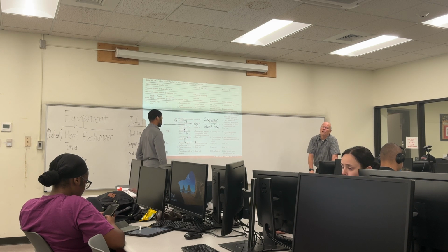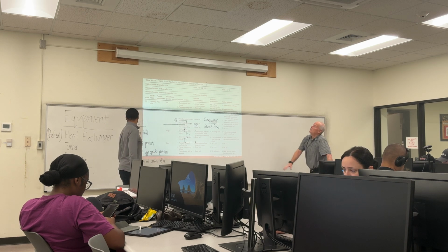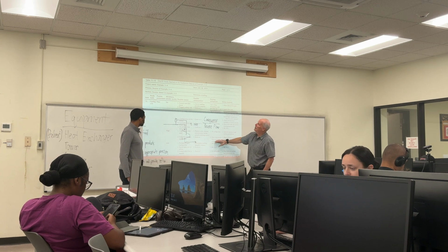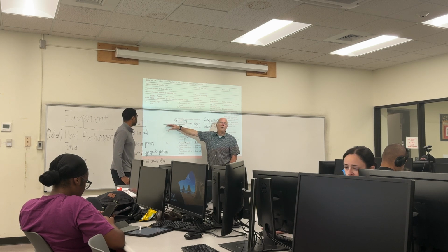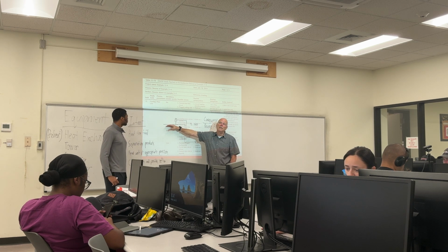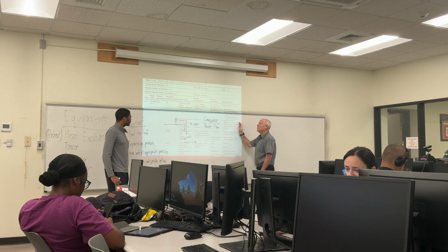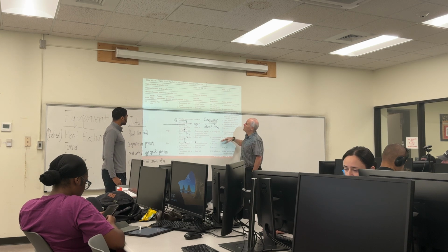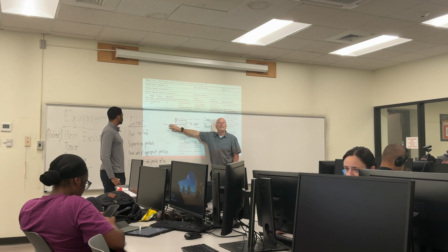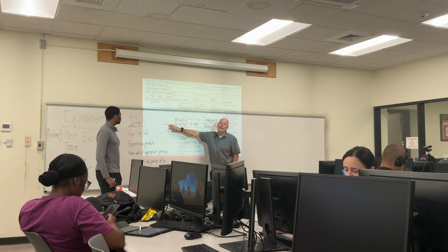You may not think so, but it is, right? They really want that flow to go in the right direction. Because if it goes backwards, what could happen? Overpressure, right? So you're compressing here. The pipeline may not be designed for that pressure that you're putting up into your unit. So if this fails and you get reverse flow, then whatever's on this side is now seeing the pressure that you are operating at.